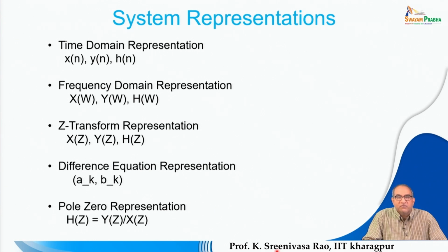So, if we want to detect the periodic segments in the speech signal, we can perform the autocorrelation, and by analyzing the autocorrelation sequence of the speech segments, we can determine whether the segment is periodic or not. If it is periodic, it is a voiced segment. If it is non-periodic, it is a non-voiced segment, or you can say a silent segment. That way we discussed the concept of convolution and correlation under the time domain representation.